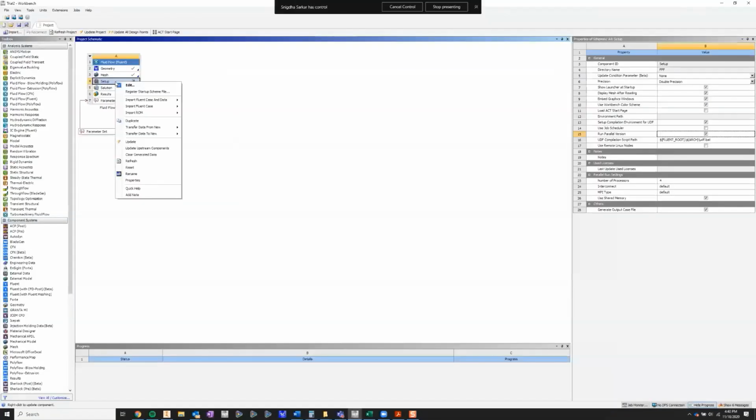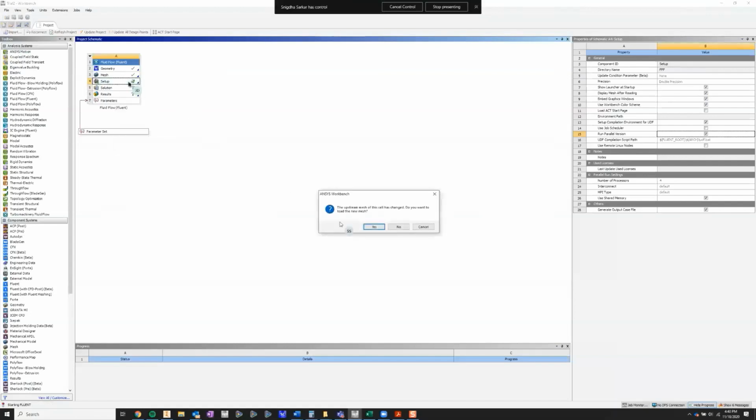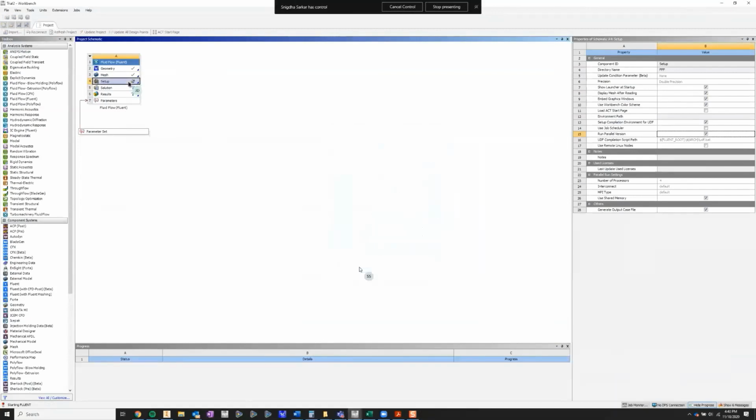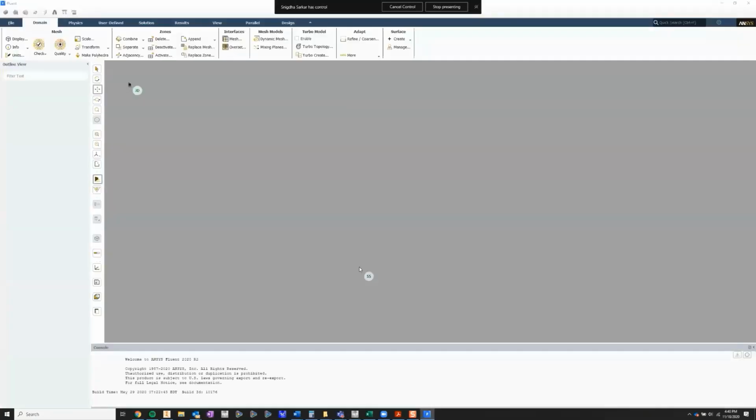And once the mesh part is done, you will see a green check against cell A3, and then we carry this over to the Fluent side of things, where we'll actually set up the flow through the nozzle.